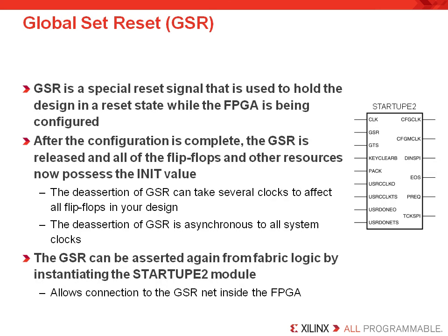Now, as I mentioned, the startup block gives you access to the global set reset network. That's the GSR you see on the primitive component on the far right. To learn more about this startup block, I again recommend you check out the Xilinx Unified Libraries Guide to learn more about its functionality. But the GSR is a special reset signal that is used to hold the design in a reset state while the FPGA is being configured. And as I mentioned, by default, during configuration, it is activated and it resets every synchronous element in your design.